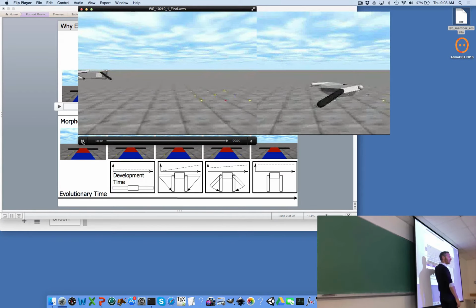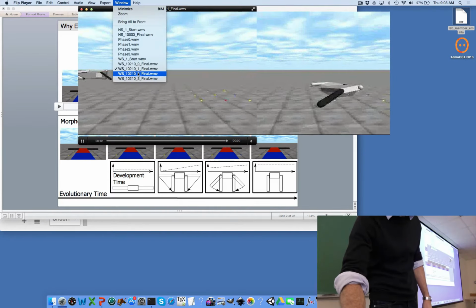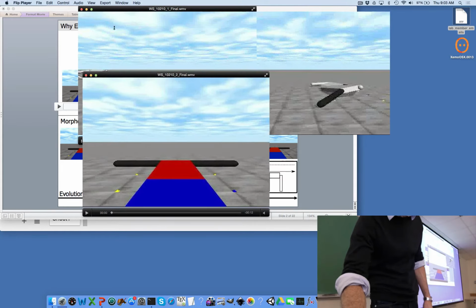Okay, so now we're at phase 2 of this one evolutionary run, and you get how this game goes now, right? Once we get this robot that exceeded this fitness threshold, we now changed the developmental trajectory again. Now we're going to start the robot with legs angled 45 degrees downward, and they're going to gradually, over the robot's lifetime, rotate from 45 down to 90 down, and the ANN is still controlling the second hinge joint as normal. Okay, so here we go.